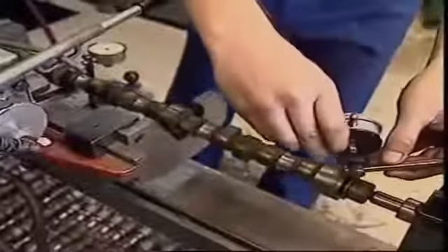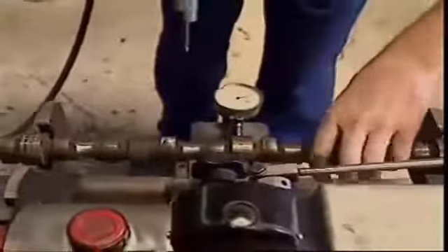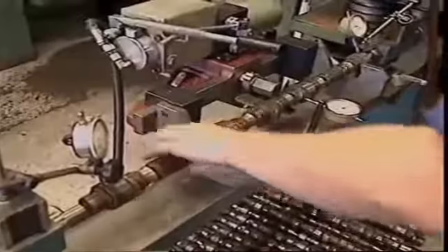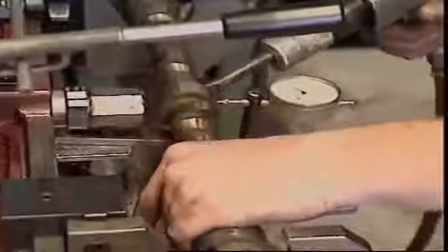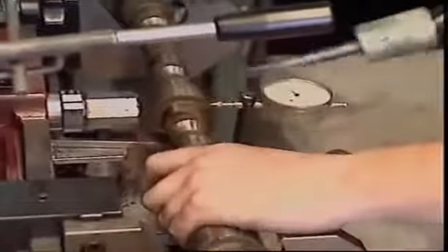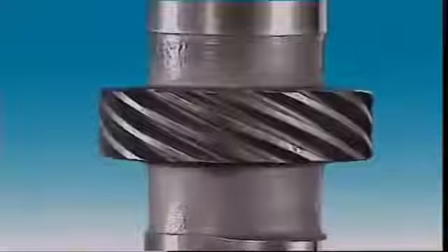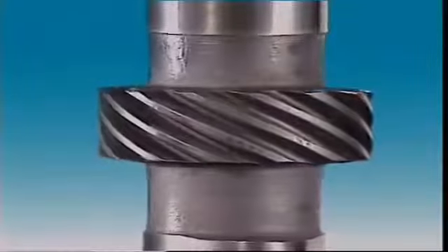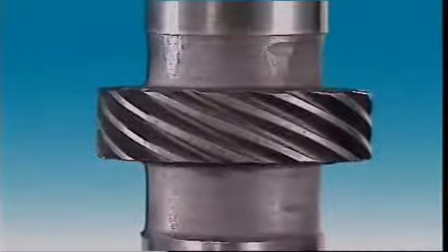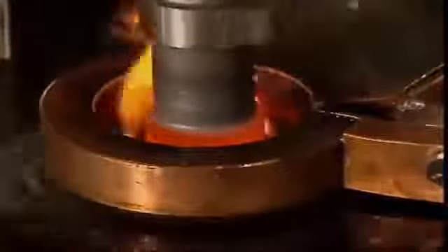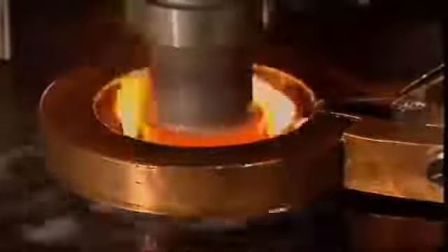If the cam is not exactly the required shape, or if it becomes worn, there can be impacts, fast valve wear, or noisy operation. The bearing surfaces on the camshaft are ground smooth, and the distributor drive gear is machined into the shaft. The cam lobes are then flame or induction hardened.